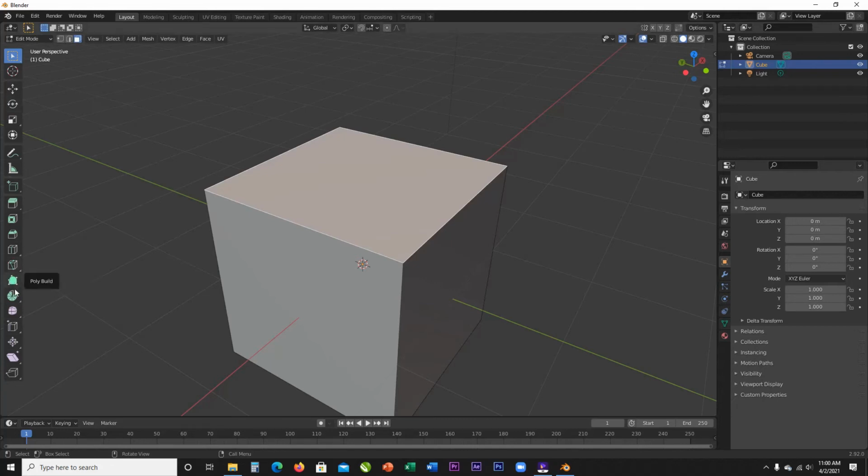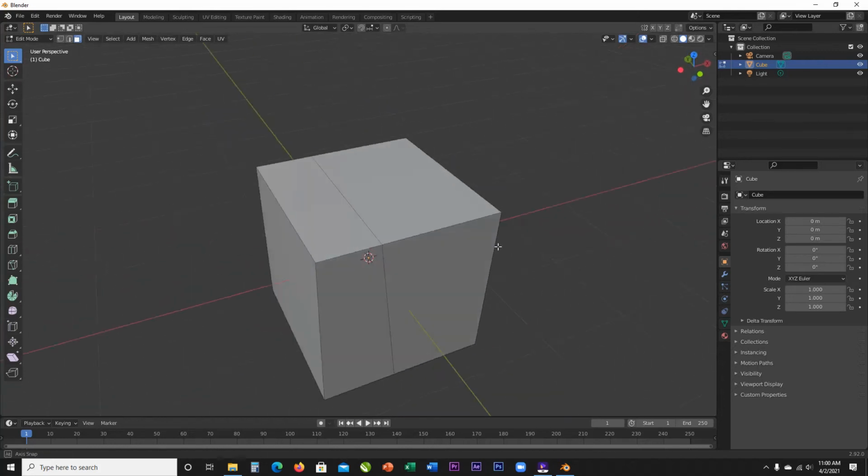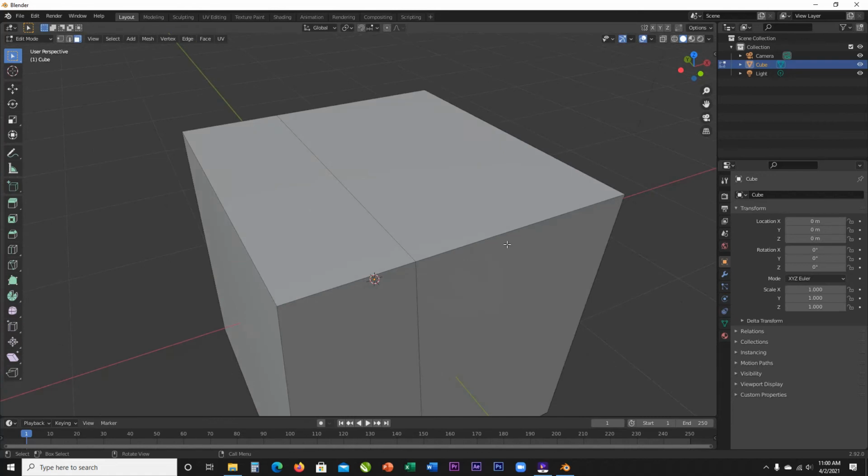This is the knife tool. It says cut new topology. You can access that by pressing K on the keyboard and then left clicking. Once you want to say that's enough, press enter and see it creates a new edge. It can be quite good at times, but I don't use it personally for most of my projects, so I'll just cancel that.